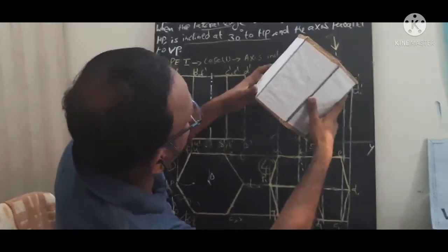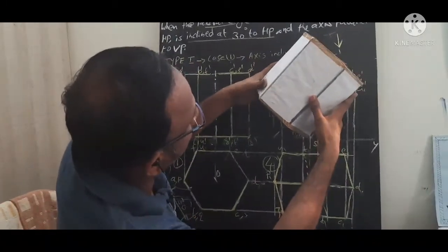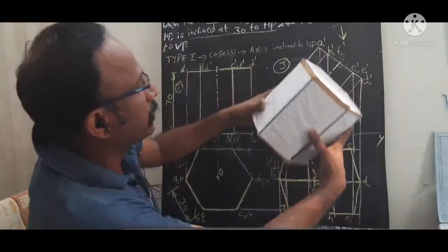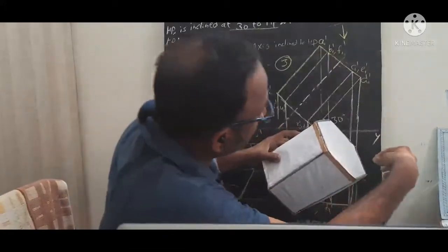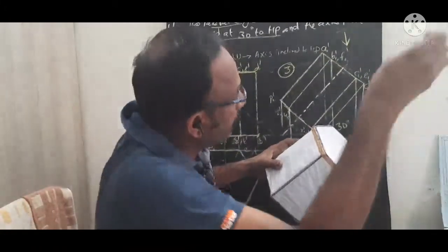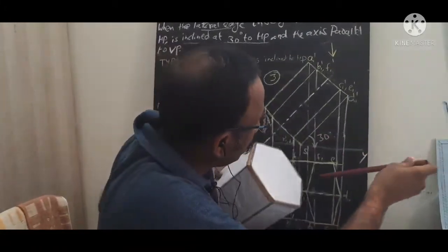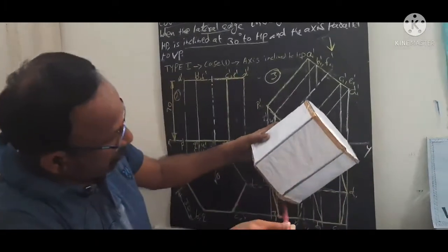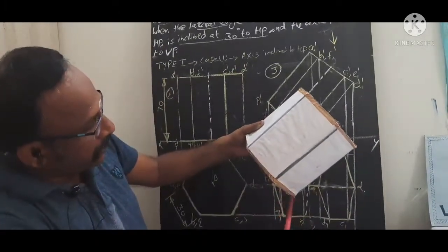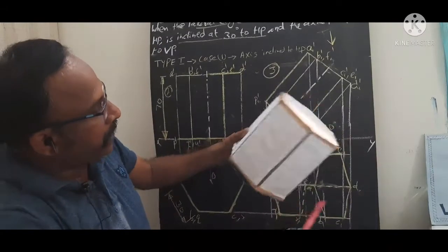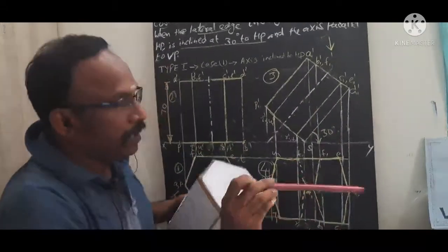Now we are able to see like this, right? We are able to draw like this. Then the corresponding top view we are seeing. While viewing from top, this area is fully visible, so we draw a dark line. Here connecting this point, the edges connecting this resting corner point are invisible, so we draw this dotted line.